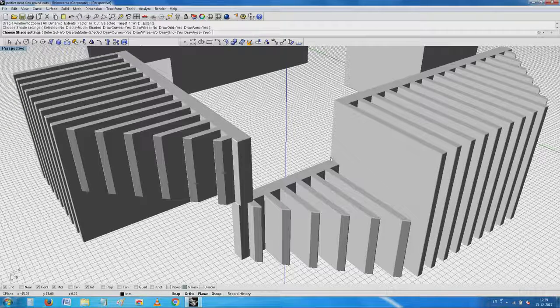which probably you can drill a small hole, insert it inside on the bottom surface, and mind you, inside I have Peltiers, and inside those Peltiers I have the aluminum tube, and if you remember, I have the corner still. I have a little access to the corners here, and once I have access to the corners, either I can leave a gap between these two heat sinks, top and bottom, so that I do not need to drill the heat sink in any way. Alternatively, I can make a small half circle, a semicircular groove here, by which it can go inside and directly take in one of the corners.